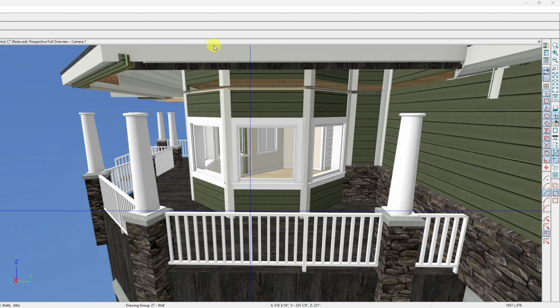So that's my goal, is to know what's going on, and then get this to the right heights so that I can get arches built in here. My goal was to get 18 inches and then a 9-inch tall arch with 9 inches of panel above, but I think I'm just going to have to go with whatever dimension makes this fascia hit, because I've got a heel height at certain areas, so I can get an R60 in my ceilings up in here with the high density blown in. So those are the major issues that I'm coming up against.